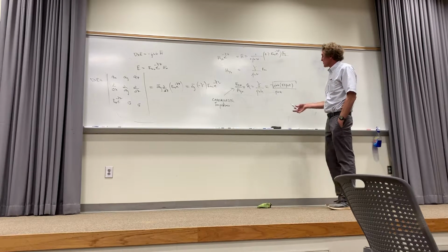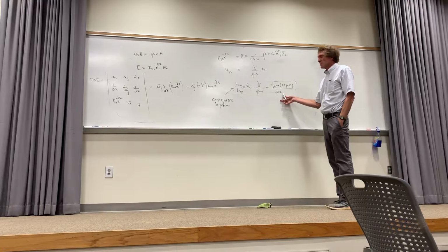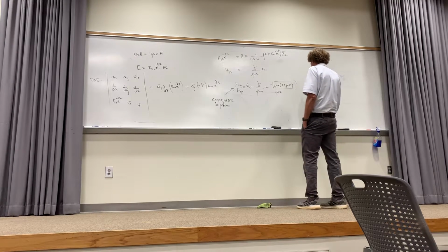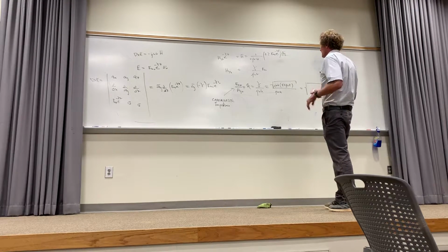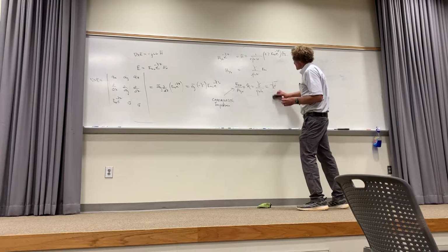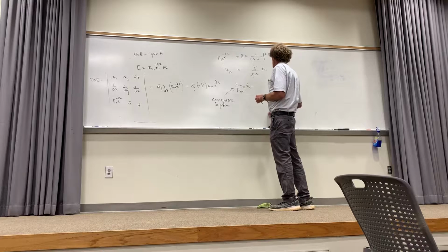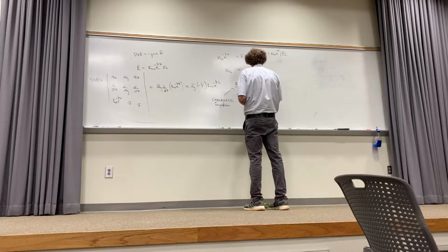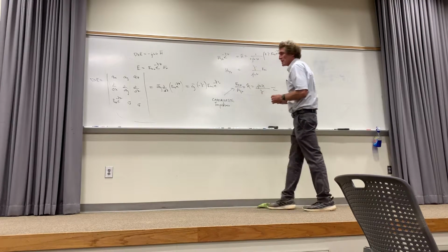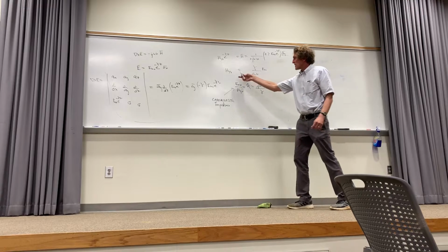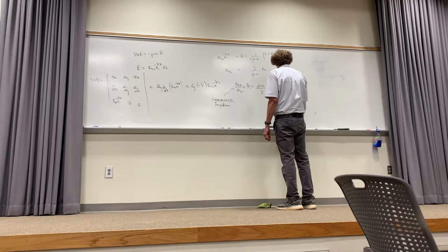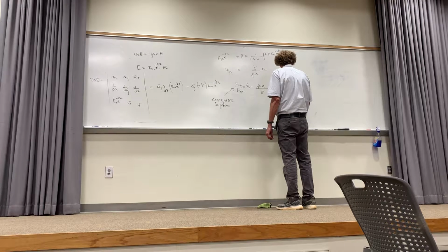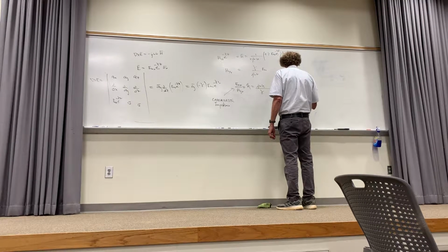Now, what happens when I do this? You see I've got j omega mu to the 1/2 power divided by j omega mu, right? So really what I have is the square root of... hold it, I've got this upside down. What I should have done is E over H would be j omega mu over sigma. My bad. I had it reversed. If I take Ex and divide both sides by Hy, I get Ex over Hy and I have to flip that. So that's equal to j omega mu over the square root of j omega mu times sigma plus j omega epsilon.